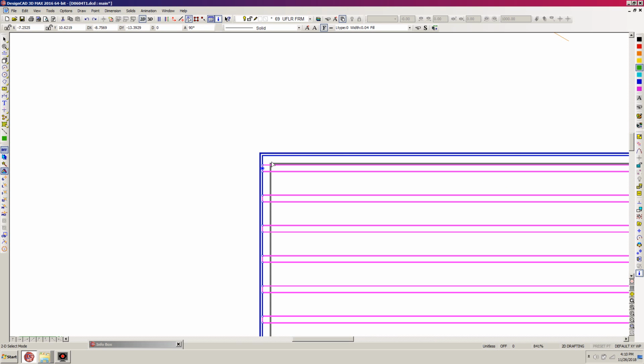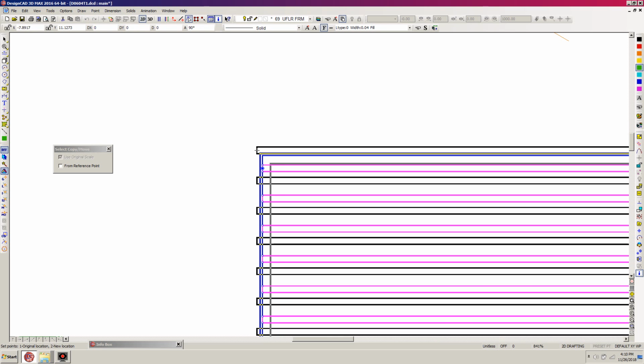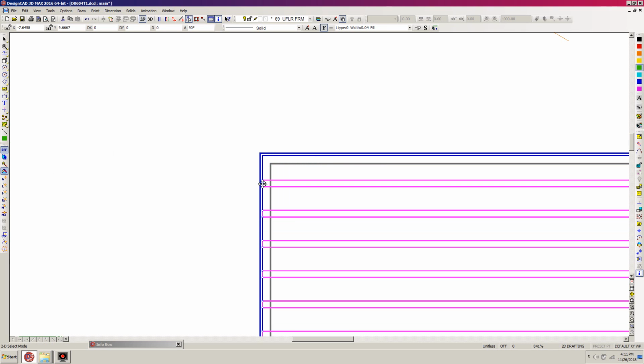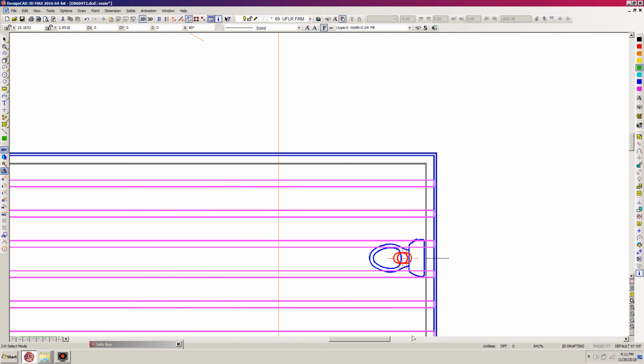And I'm going to hit M again, and gravity move using the comma. And so we're still at our 1.25 inches on the X tab. We're going to go to minus 16 inches. That should work more effectively. There we are. Okay, so that looks better. Let's take a look at our toilet. Look at that. So that works.